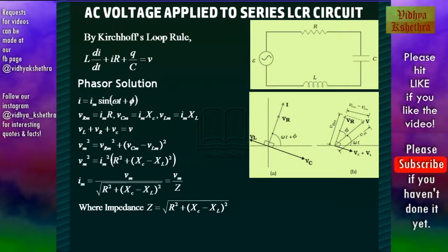Now VRm, which is the voltage across the resistor, is given by ImR. VCm, which is the peak voltage across the capacitor, is given by ImXC, and VLm, which is the peak voltage across the inductor, is given by ImXL. Here XC and XL are the reactances. Now we can write VL plus VR plus VC is equal to V. That is the total voltage applied to the circuit.